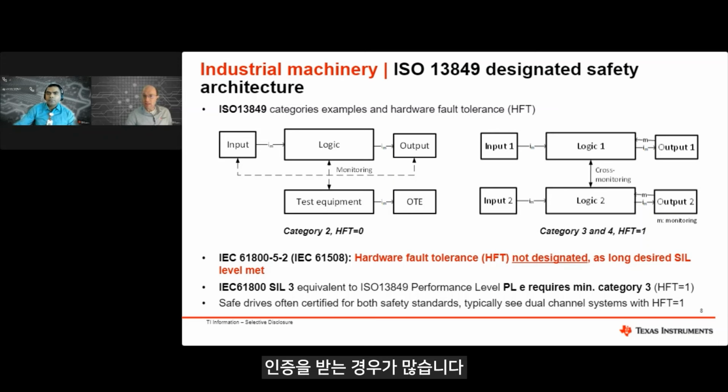In architecture 2 in the middle, we have channel B, which cuts off the power to the anode or the logic supply, in case of CMOS gate driver, of all 6 gate drivers. The second channel, channel A, cuts off the isolated supply of the secondary side of all 6 gate drivers. This approach might be very suitable for multi-channel digital isolators or half-bridge gate drivers. Architecture 3 has 2 redundant switches in series and cuts off power to the isolated supply of the secondary side of all 6 gate drivers. In that case, it typically requires 2 24-volt rated load switches. On the other hand, it may be easier to retrofit to an existing non-safe drive.